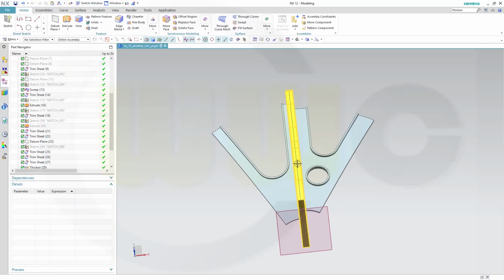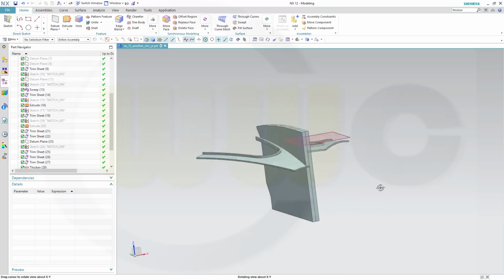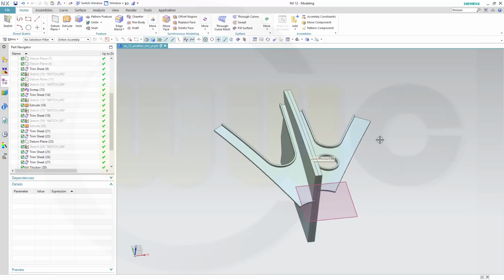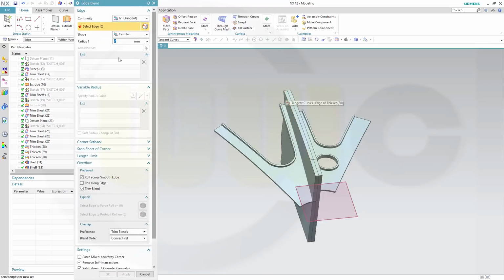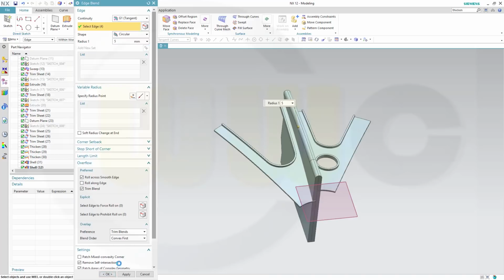So I will need this one on that side and on this side to get a circular pattern. But first I could add the fillets. No, first I have to put this on both sides. So maybe let's do a blend up here first. Go for 5 on this edge and that edge. Okay.